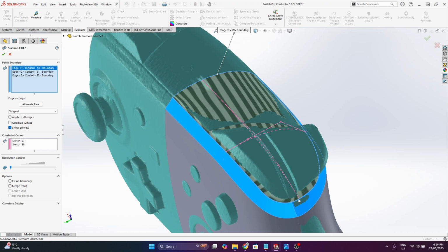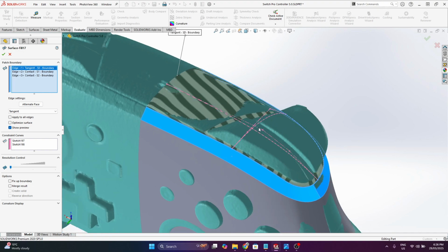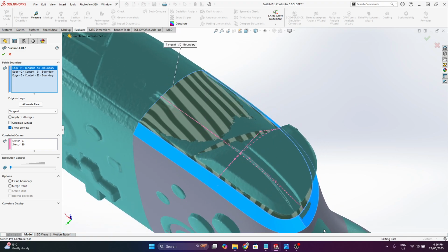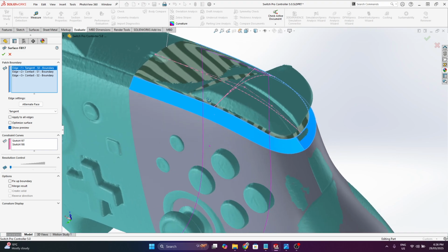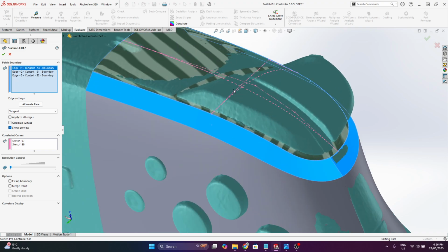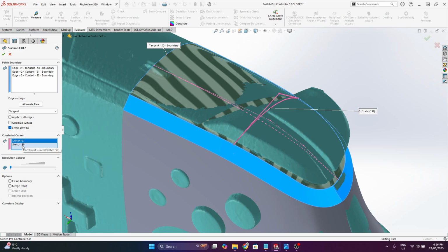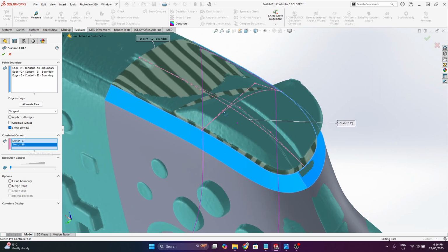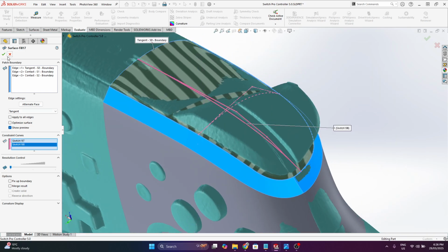It's essentially assuming that the 4th edge is infinitely small. The surface fill tool can deal with that because internally in SolidWorks it overbuilds the surface and trims it back. Sometimes with the surface fill tool it does funny stuff, but again you can come in and add guide curves. So yeah, more or less did that here.